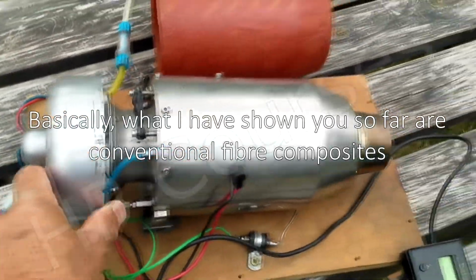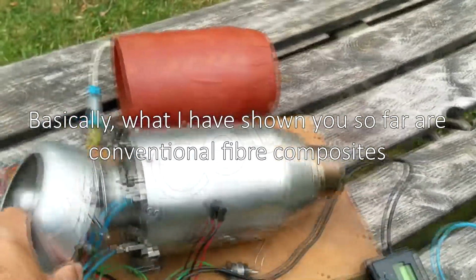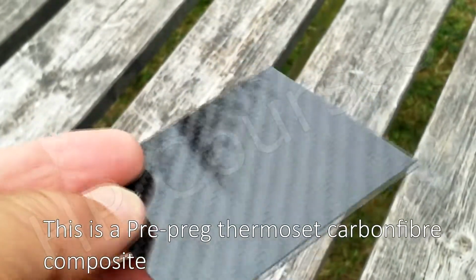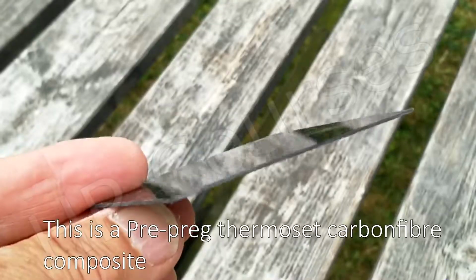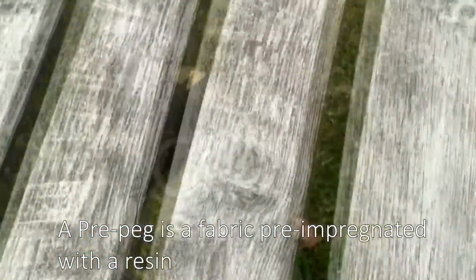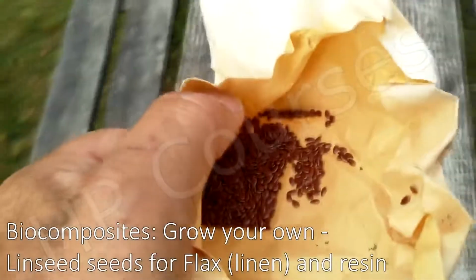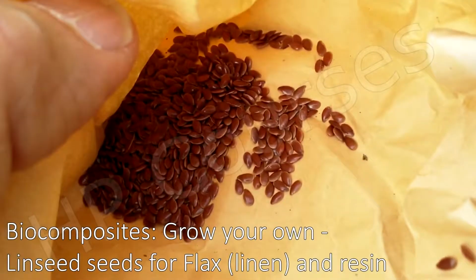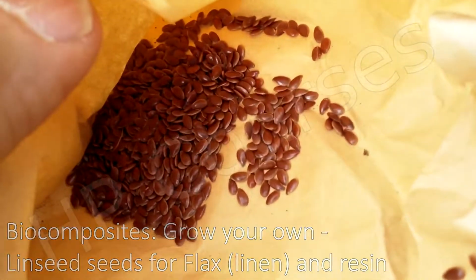What I have shown you so far are conventional fibre composites. There are other types of composites of a different nature. Prepregs are composite materials in which a reinforcement fibre, such as carbon fibre, is pre-impregnated with a thermoplastic or thermoset resin matrix. Grow your own composites, a biocomposite, which derive from biological renewable resources.